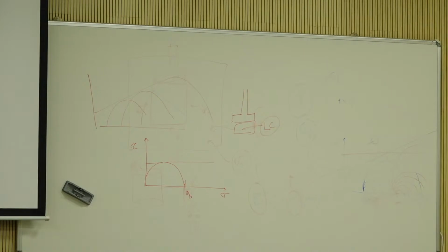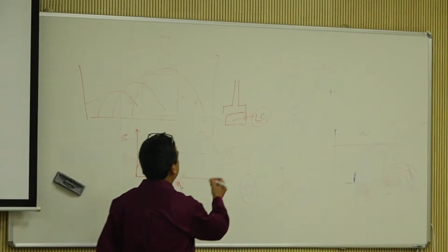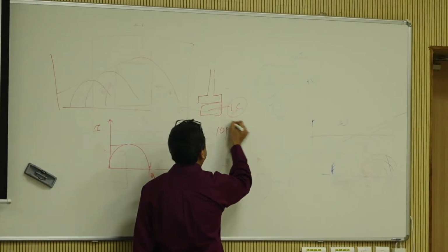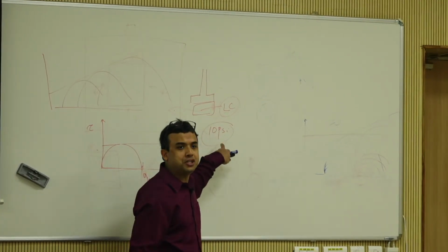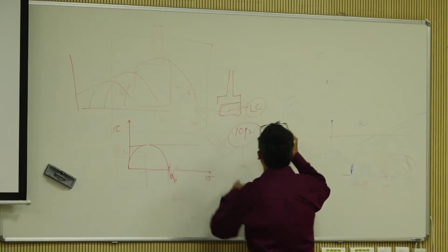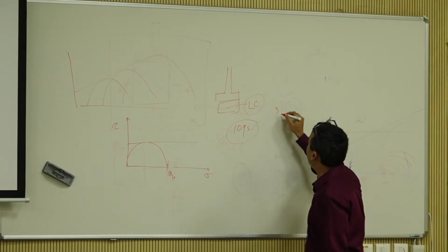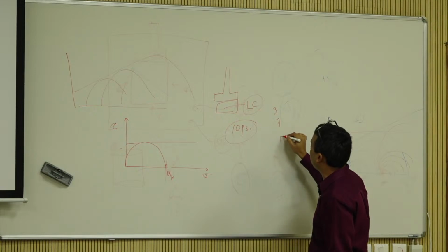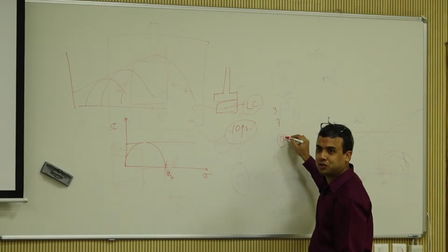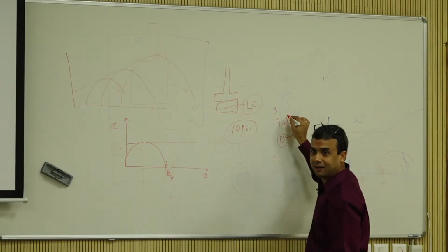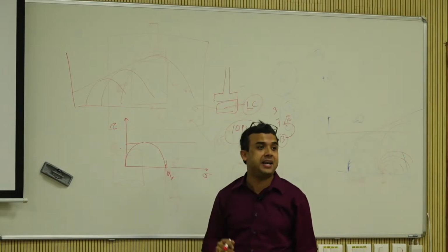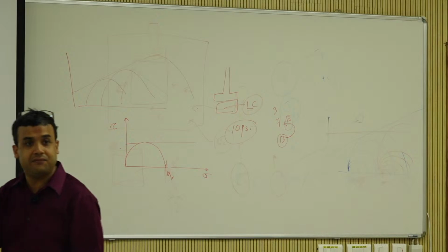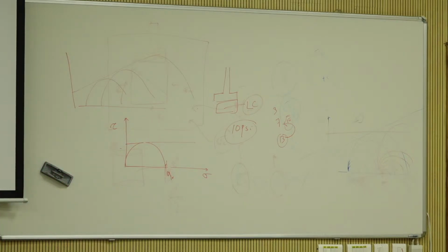So when I am applying, my target stress is, say, when we go into resilient modulus, you will see this. When my target stress is 10 psi, the load cell, or the pressure cell, keeps measuring it, saying that no, I'm at 3, go up. So then you go up to 7, like no, still keep going up. Then you go to 13, it's like no, too much, go back, 10. This keeps happening at 1,000 times per second, at a very, very fast rate, right?